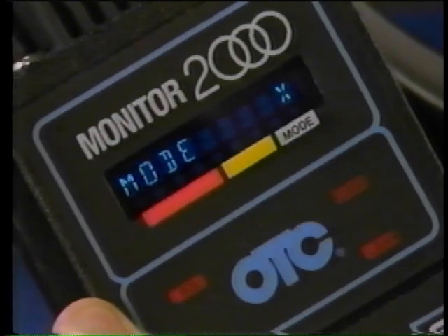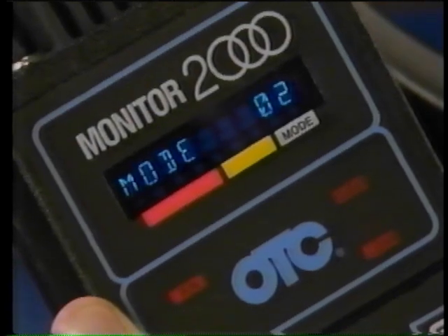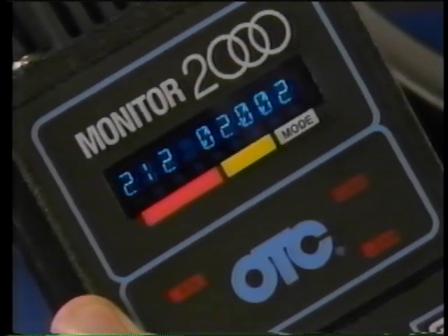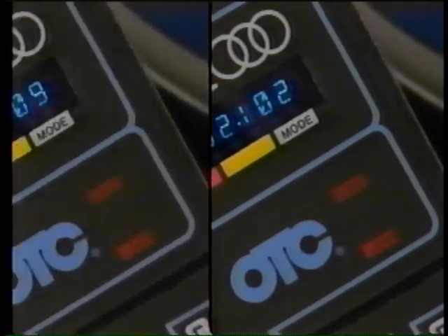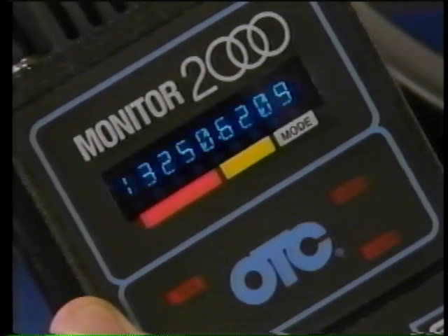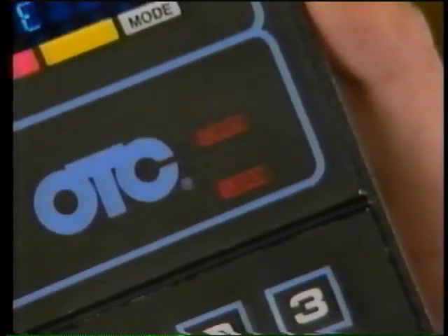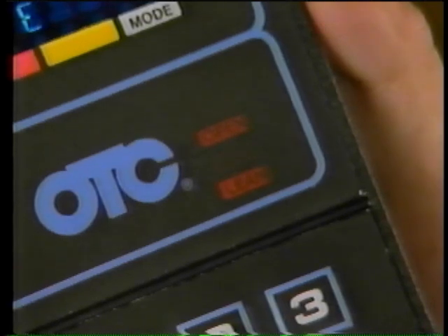This will cause the tool to erase the mode that you were in previously and ask you for a new mode number. Since you want mode number 2 to check the coolant temperature, press 2. Now the display will show you the coolant temperature. Since the temperature is over 80 degrees centigrade, run the engine above 1200 RPM for 2 minutes. At this point, the scan tool should indicate closed loop. But in this case, you only get open loop.